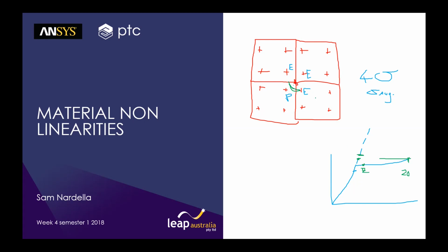So you start asking the question, well, what's going wrong? So remember this extrapolation is based off distance. So the only way to move these integration points closer to that point there is to use a smaller mesh. So in that way, your extrapolation distance is reduced.